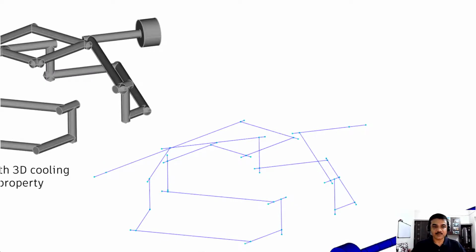I mean to say, this could be your inlet, and then there could be an outlet at the very extreme end, but in between there could be open-ended channels or crossing channels, the way we drill them in the mold. Now with 2018.2, we can represent the cooling channel as you manufacture it, or the way it is represented in a mold design.